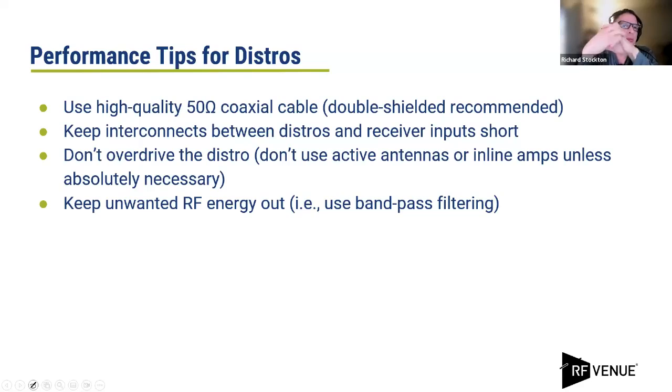The only time I've ever used an amp is when I knew my cable run was longer than expected. With cable runs for integration versus live, most likely for live you won't need an amp because you're not going to be really far out with a cable run anyway. An install is different, and if you calculate the signal loss per your cable, you may decide to use an amp just because you had to go maybe 50 more feet than you thought you did. But if you use the right cable, and we can go over the cable types that work with different lengths offline, just don't fall into the just get an amp for everything trap.